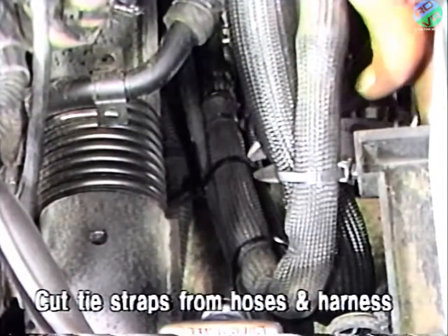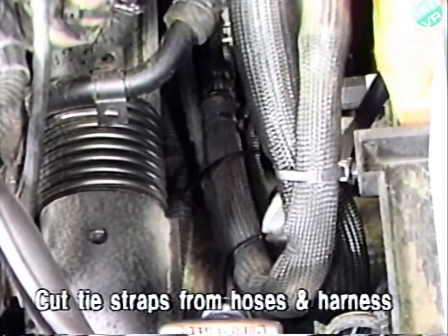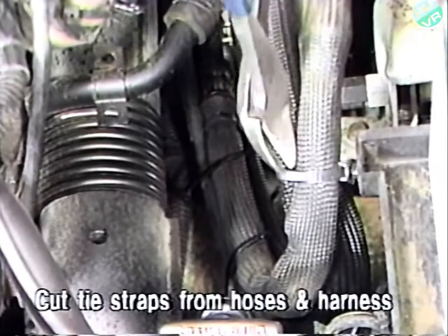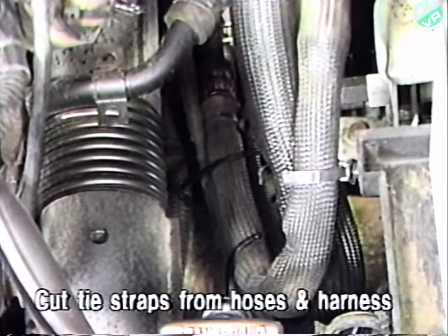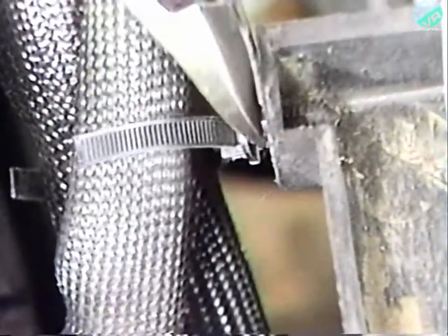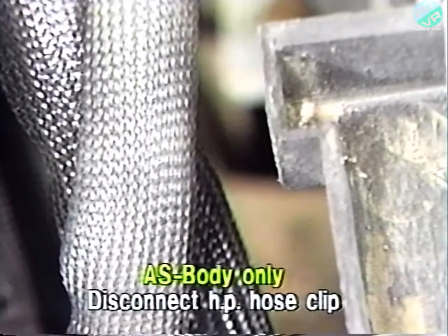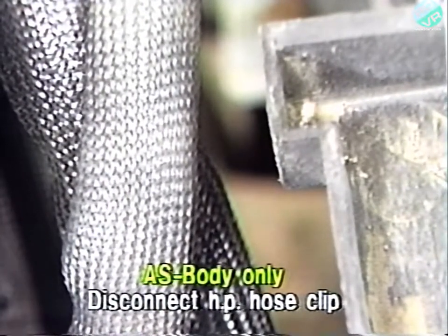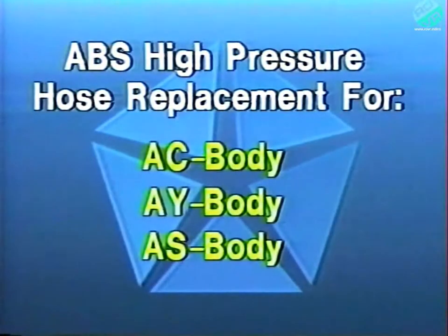Next, cut all the tie wraps attaching the high-pressure hose, low-pressure hose, and wiring harness together. For visual clarity, some wiring harness connections have been moved aside. On AS body vehicles, you will also have to disconnect the high-pressure hose clip from the battery tray, as seen here. The following steps will demonstrate the high-pressure hose replacement procedure.